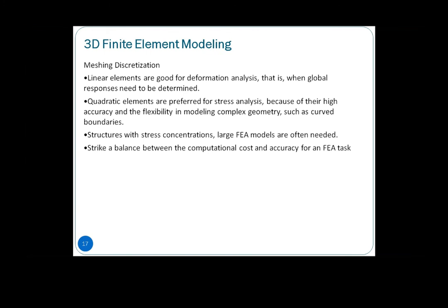So meshing discretization. Just to repeat back, linear is good for deformation, quadratic is for stress indices. So we have to find a cut-off point, or strike a balance between the computational cost and the accuracies that we have mentioned. So the mesh independency test is very important in this case.